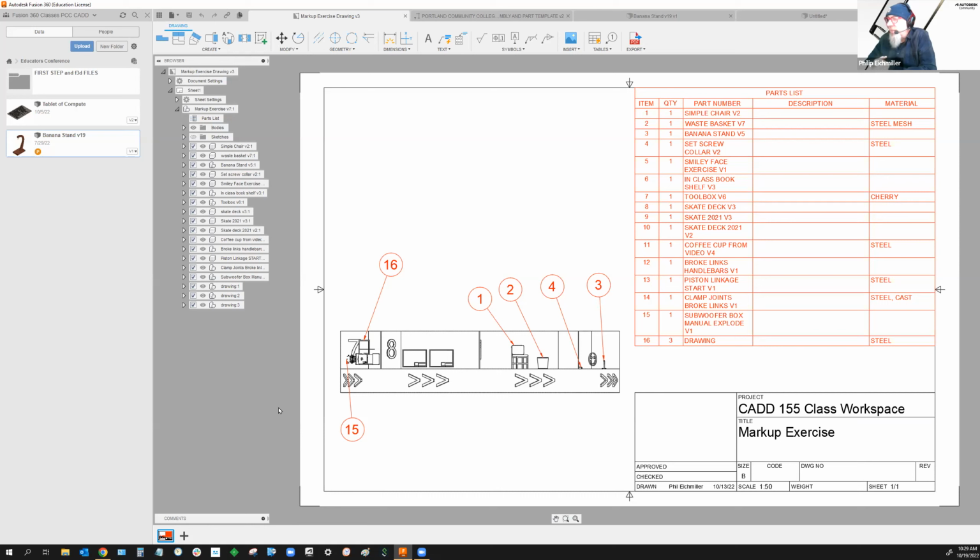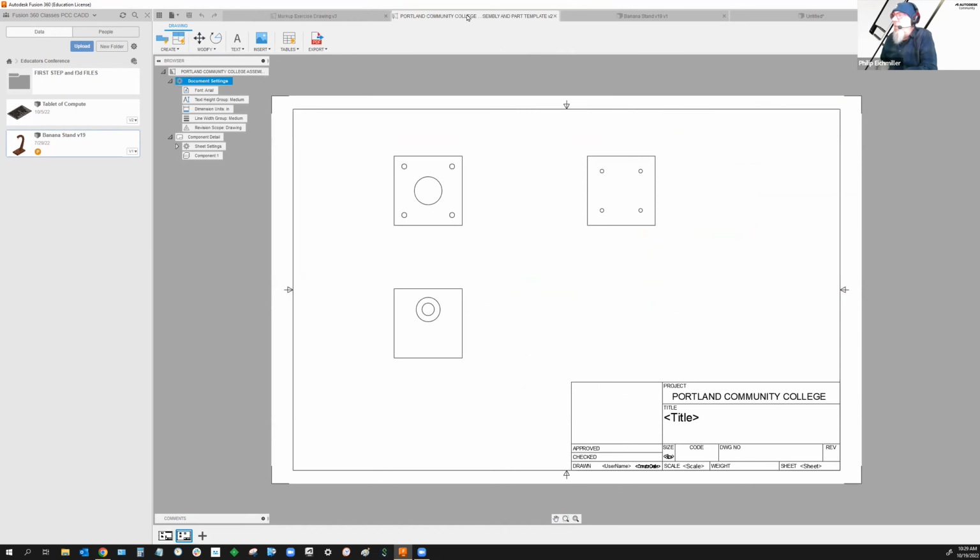It's the fact that we have colors now. Right? That's simple. Colored ink. We have colored ink, and so I'll show you what it looks like. So here is a template, right? I created a template by going to here and saying, I want to make a new drawing template. And when you make the new drawing template, now you don't have to do this only in the template, but the template's the best place to do this if you make lots of drawings.